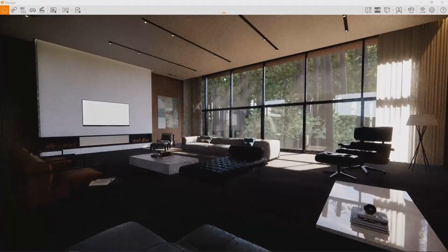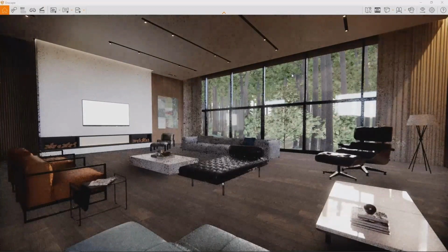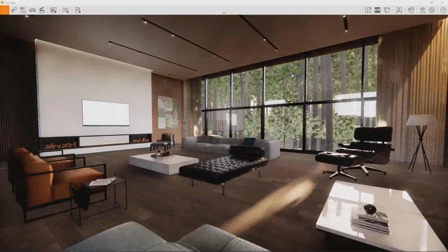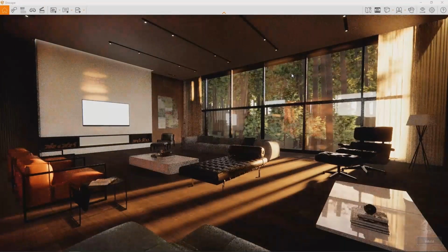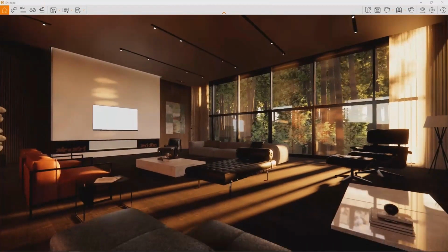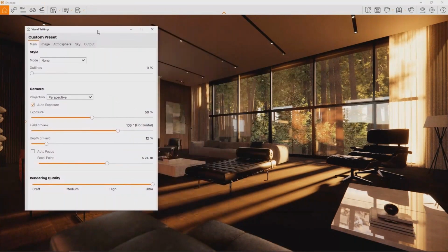Playing around with the sunlight here, we can follow the natural light angle, the natural sun path, or we can break the sun trajectory and use, for example, Control U and I or Shift U and I on the keyboard. Or you can also review those controls by pressing the H key in Enscape, and that way we can move it to the position we want it to be.